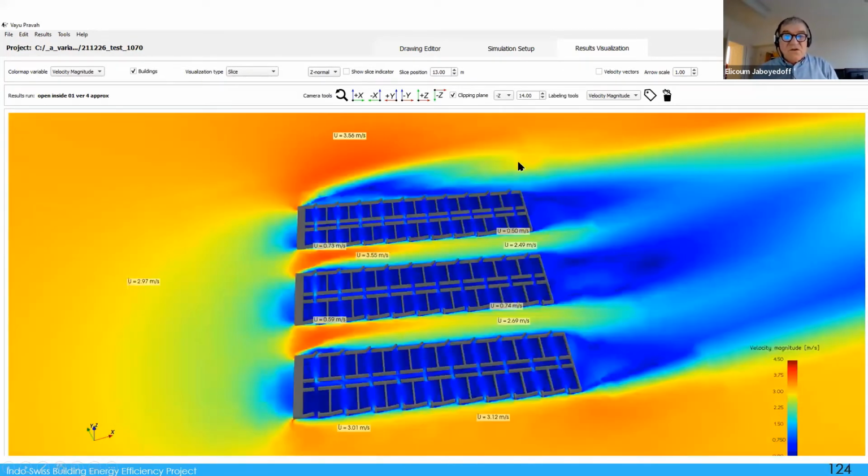Now, if you change the orientation of the building, having the wind going along the facades and having this kind of special items to catch the wind, you can see that most of the flats have quite reasonable velocity of wind. And comparatively, you can see visually that the airflow is quite well distributed. It's not perfect, of course, but it gives an idea that if you have, let's say, adjustable components like window openings and stuff like this, people could adjust somehow their own cross ventilation by playing with the windows or shutters that you could have.